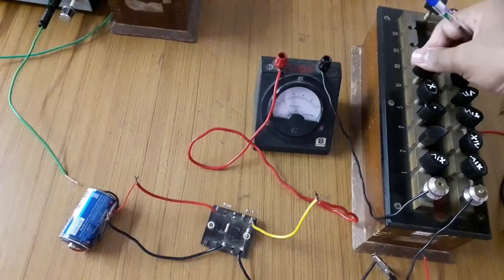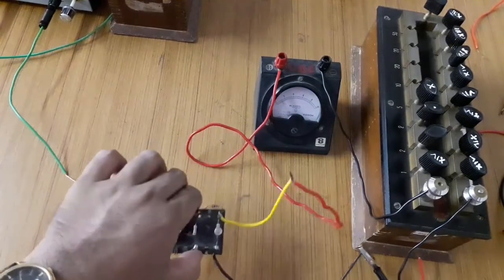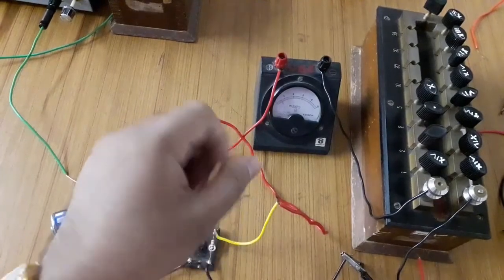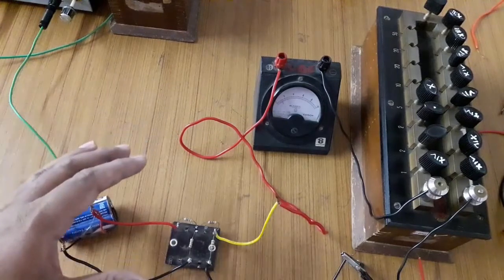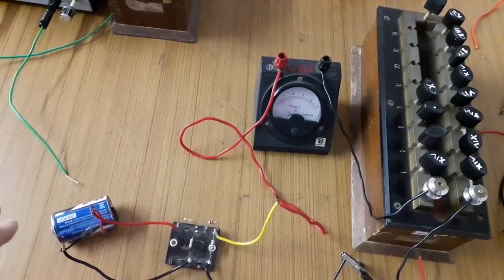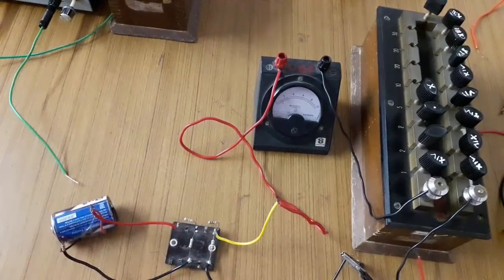And so let's take out 90. It's 1.4, and let's take out 100 ohms. It's 1.4. Fine. So with this we have finished the first part of the experiment, and in the second part we are going to replace the circuit and connect the resistance 75 ohms which we have already calculated, and the Norton's current, which we have calculated to be 4.74 milliamperes. We will connect it parallel to the circuit. So see you in the second part.